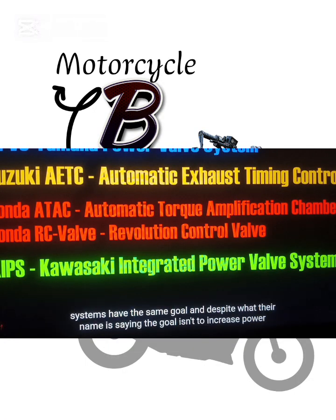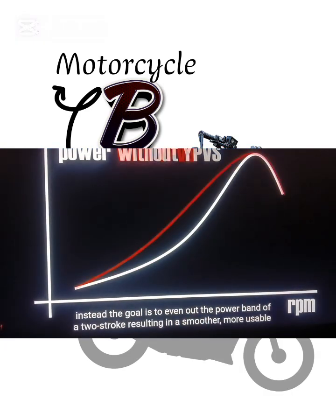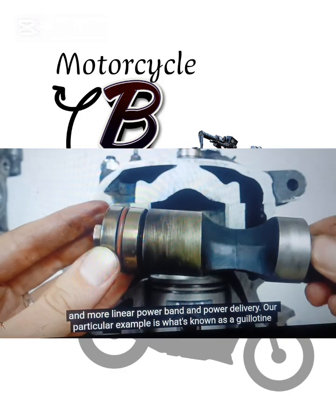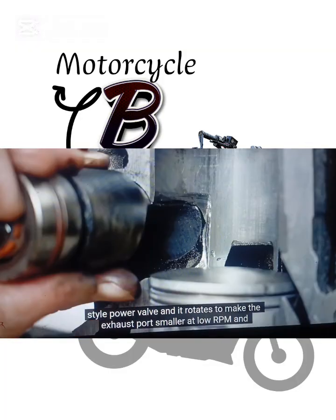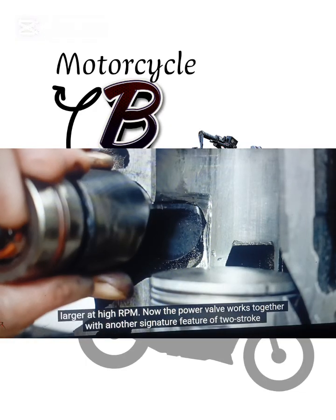And despite what their name is saying, the goal isn't to increase power. Instead, the goal is to even out the power band of a two-stroke, resulting in a smoother, more usable, and more linear power band and power delivery. Our particular example is what's known as a guillotine-style power valve, and it rotates to make the exhaust port smaller at low RPM and larger at high RPM.